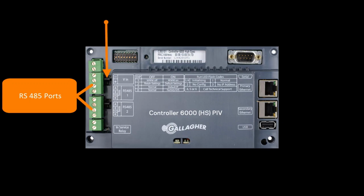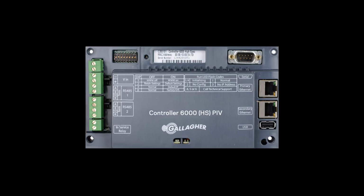Termination jumper plugs are required to be fitted if the controller is being used as the first or last device on an RS485 bus run. On 6000 controllers, RS485 ports can be configured as G-bus or H-bus.